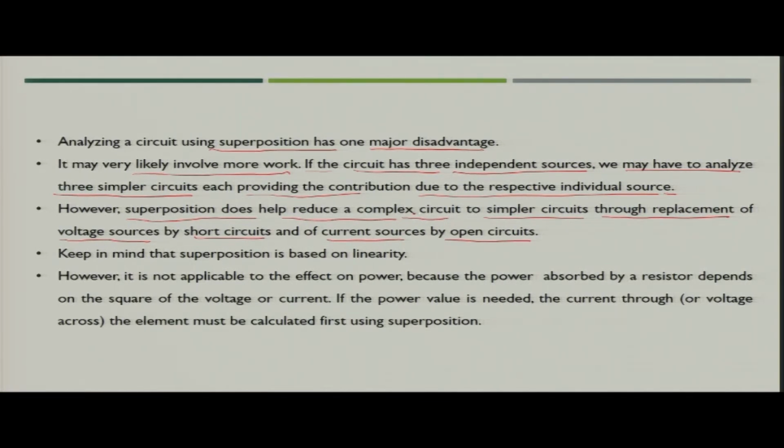So, using the superposition theorem, although you are analyzing multiple circuits by taking one voltage source or one current source at a time, eventually you may get the solution very early, because the circuits are now simpler as compared to having the multiple sources connected and analyzing that circuit. And the superposition theorem is based on linearity. So, it is easier to analyze and then add the responses individually to get the final outcome.